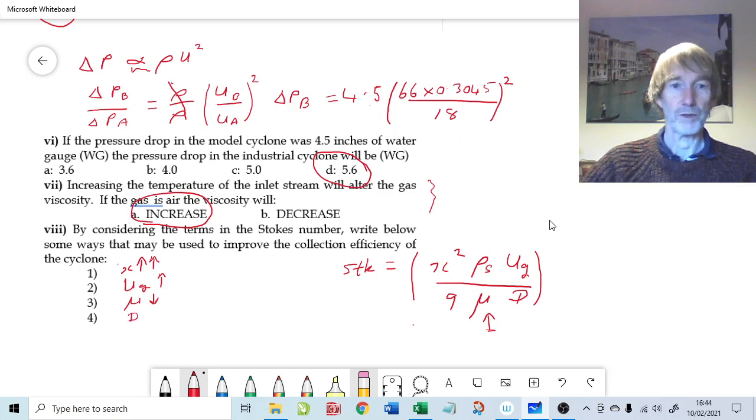And then the final one that we want to do is to reduce the diameter of the cyclone, and that comes back to what Dyson did with his cyclones that we use for vacuum cleaners, his bagless cyclones, because instead of 1 or 2 large cyclones, he moved about 10-20 years ago to a parallel collection of much smaller cyclones, and that of course is because D is underneath.